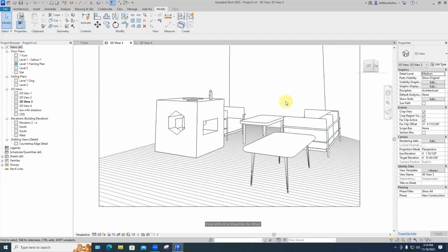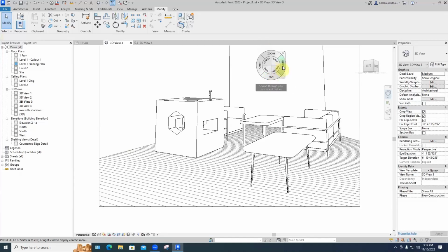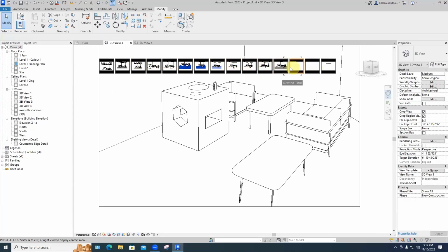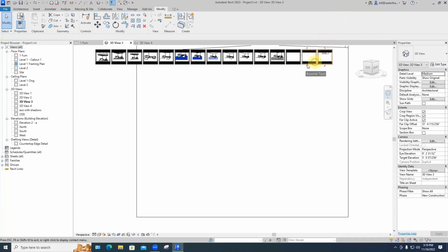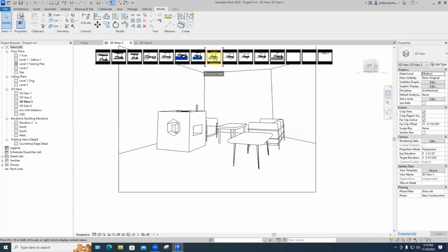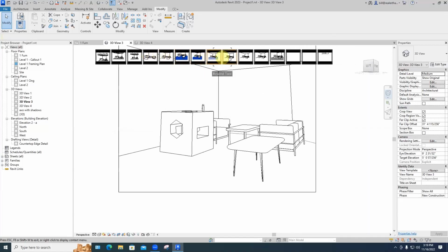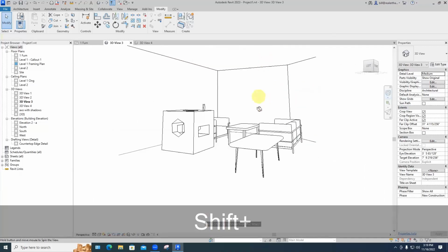Jimmy, you like that? That's Shift W, the navigation wheel, which brings up this guy. And then on rewind, you can go back and look at your previous views, which is really nice when something like this happens. Like, where am I? And it's just for that view. It's not going to do it for all of them. It doesn't regress the model in time. It's like the current state of the model seen from those previous places. It's not taking us back in time. That comes later. Okay, that's all I got.